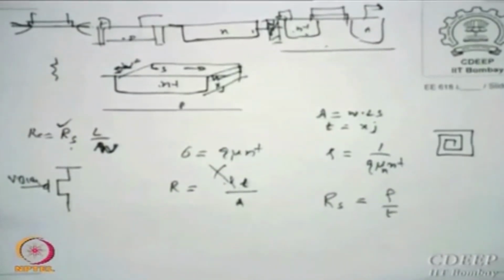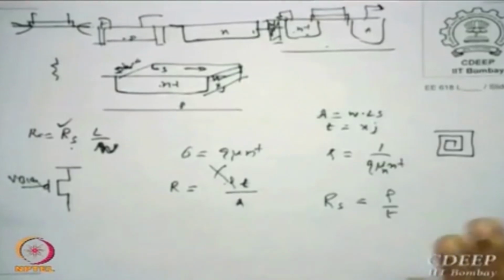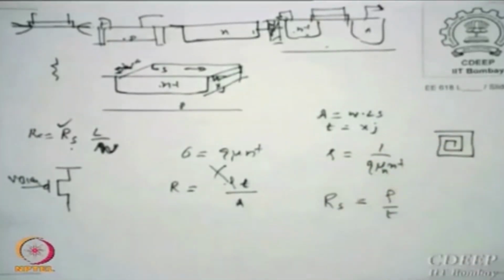Then should we not really put a resistor to compensate? That is what bandgap reference people do, they actually put a resistance to compensate. They do not put a MOS device or any other device to compensate, they actually use a resistor because it has the opposite sign of TCF, so you want to subtract. So please remember different components have different ways of being looked at in a given circuit.